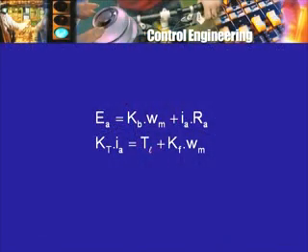So either the value that we chose was not correct, or was not known accurately enough, or has changed now because of operating conditions. What will be the effect? Now, as you can expect, if Ra is greater than what it was calculated or assumed to be, then the back EMF term will decrease a little bit, so the speed will decrease a little bit. But you can see that the effect of the change in armature resistance on the change in speed is going to be much less, because there is 20 volts in comparison with 210 volts.